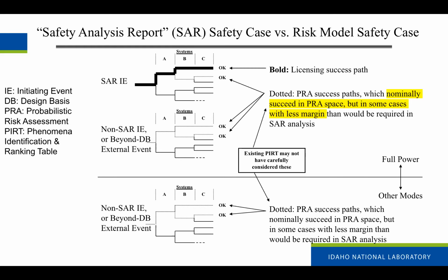But in another path, and I have in mind here feed and bleed for pressurized water reactors, that's not really analyzed in the safety analysis report necessarily, or it certainly wasn't a generation ago. So while people have done backflips to achieve enormous margin in the design basis response to the design basis challenge, much less was done to establish the viability of feed and bleed.